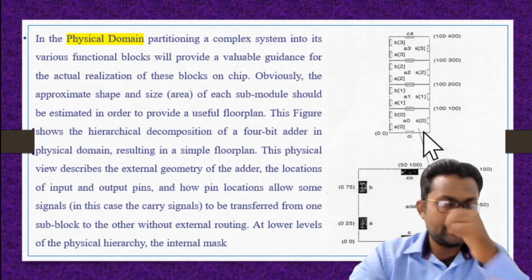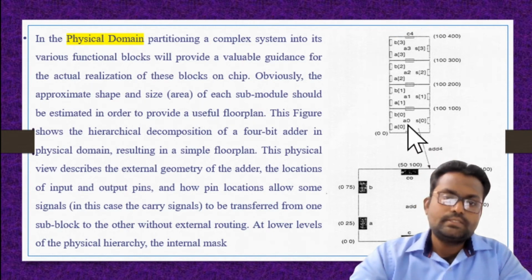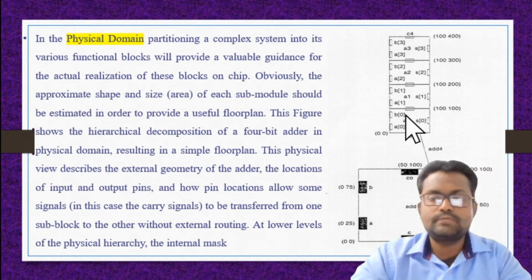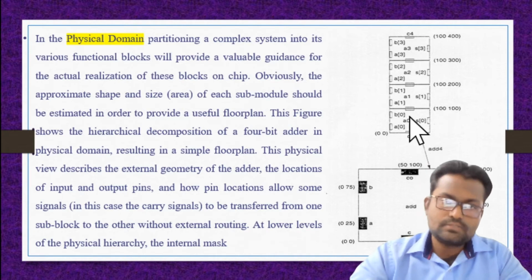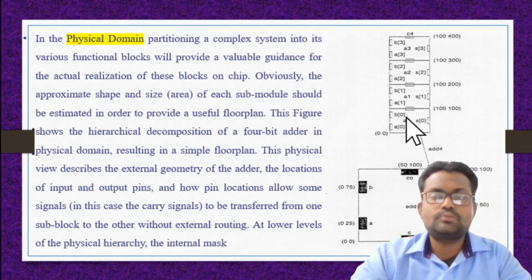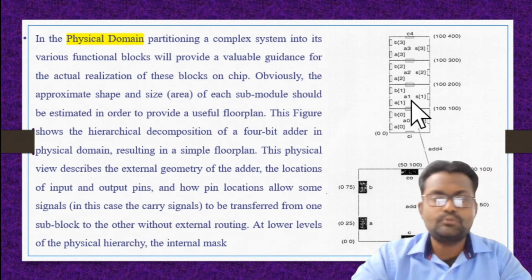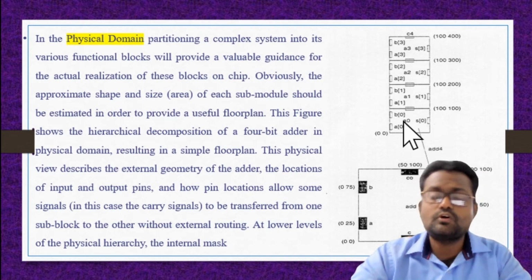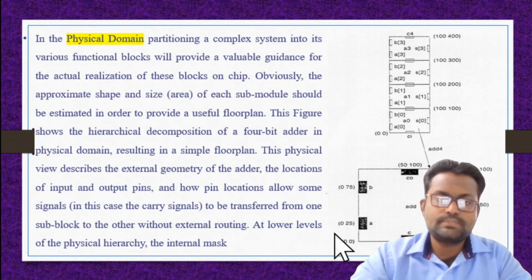Here the structure of a single bit adder is represented. Here 4 single bit adders are represented, and we connect each to the neighbor of the previous one. So the spacing between the two single bit adders is very small, so that we can easily provide the carry output of one as an input of another. The individual position of inputs and outputs is represented by this diagram.